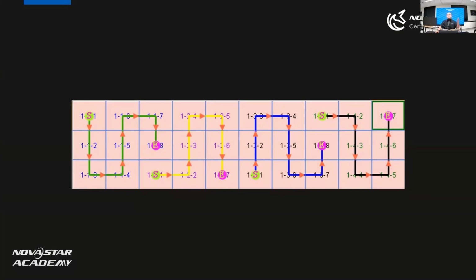So this is the final connection that the customer sent to me. Let's see whether it is okay. After the calculation, one output can connect 8 cabinets. So we can check the interface from this connection. One output, 1, 2, 3. Okay, 8 cabinets should be possible. The second output, only 7 cabinets. Should be no problem. So if we calculate as at the beginning, it should be okay.